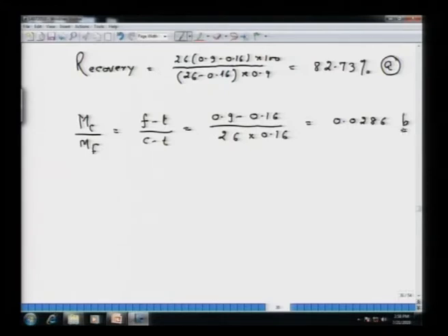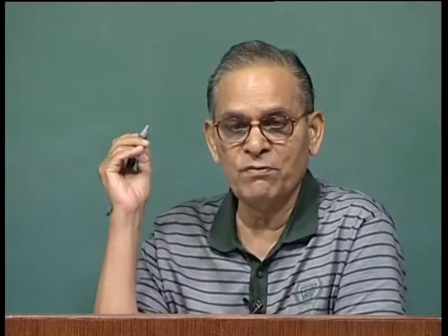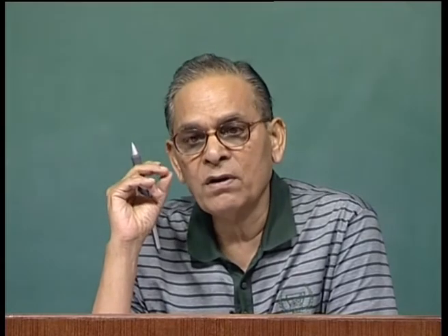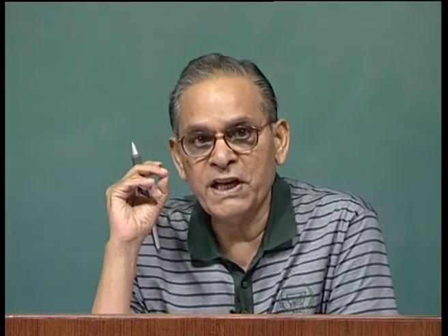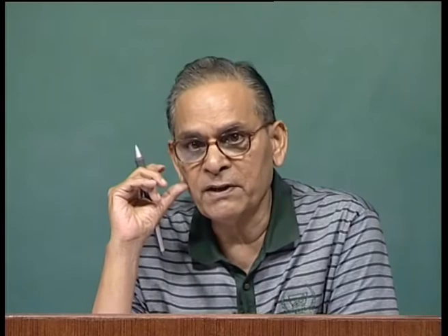Now, you see that the concentrate is hardly 2% of the feed. So, a large amount of tailing is produced. The message that I want to give from here is that one of the important considerations in metal extraction is upgrading the ore in the mineral beneficiation, and as a result of upgrading you produce a large amount of waste, and that point is to be understood.